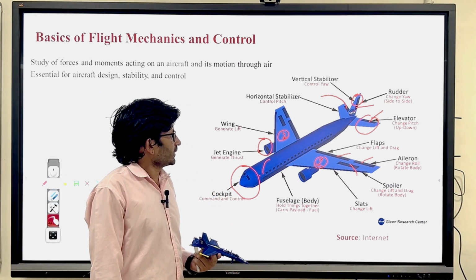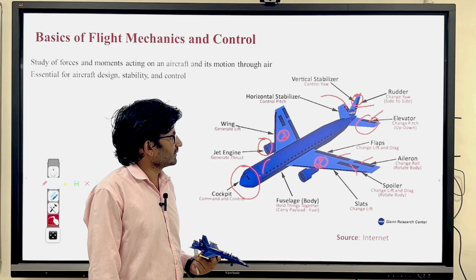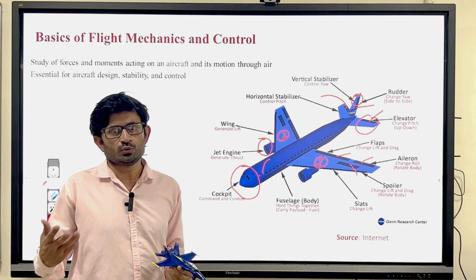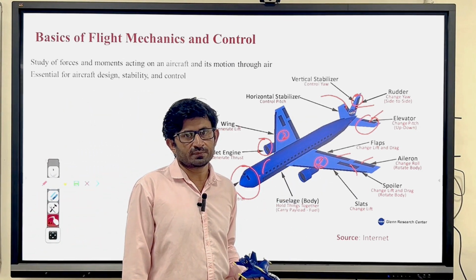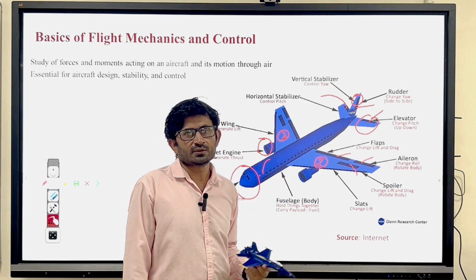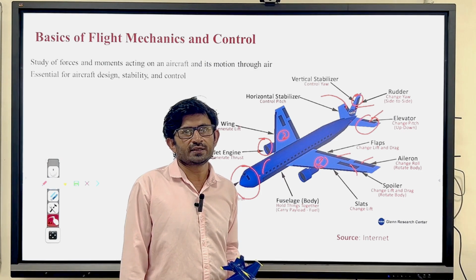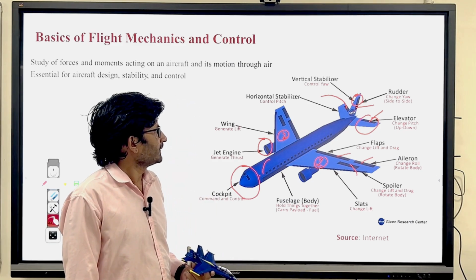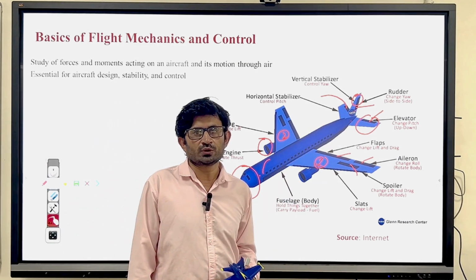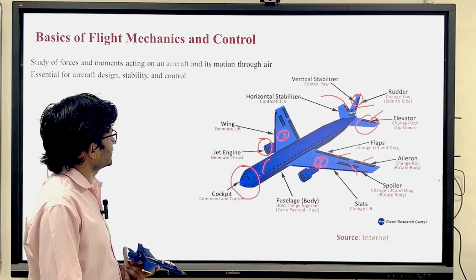I will tell you some more detail. Apart from the basic control of rudder, elevator and aileron, there is another job to do. For example, the rudder will be used in an asymmetric power condition. The rudder can be used in spin recovery. The rudder can be used in the crosswind landing case, and the aileron can be used for yaw also. Differential elevator can be used to roll the aircraft also. These things we will cover in detail in the aircraft stability and control part.